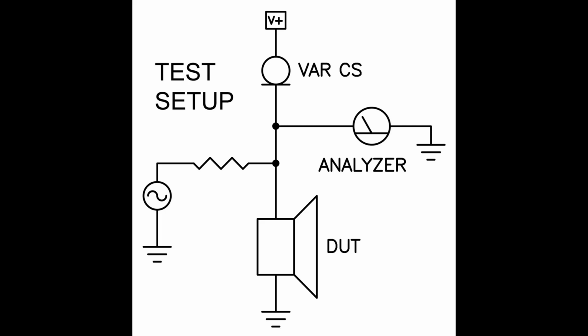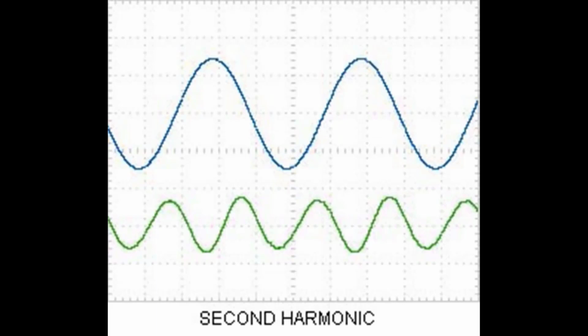First off, what does the distortion of the average cone loudspeaker look like in this test without any bias current? With a few exceptions, I found that it was second harmonic with negative phase alignment, as in this example. How weird is that? To be sure, I tested the apparatus with a resistor instead of a loudspeaker. And no, it was the loudspeakers. Maybe speaker designers figured out the second harmonic trick long ago. Anyways, following are several examples that I tried.